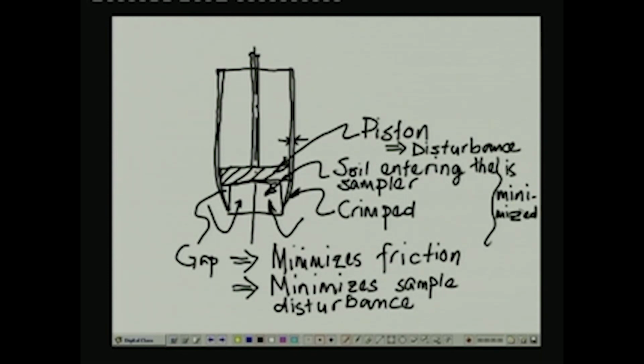Okay. So, what are the measures then? We have to have a thin walled sampler, with a relatively large diameter in comparison with the wall thickness of the sampler.